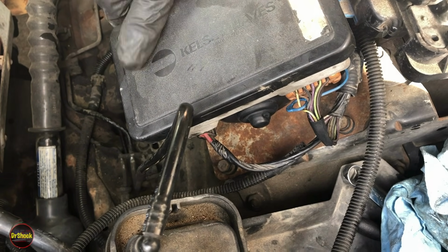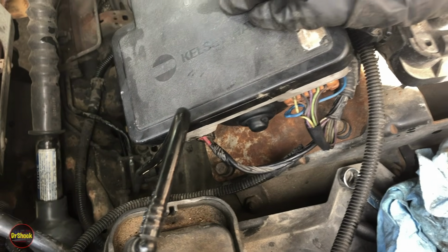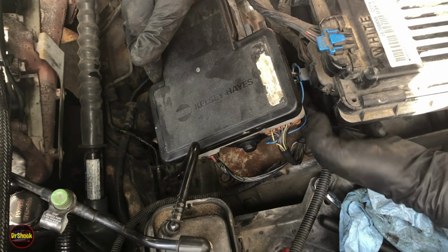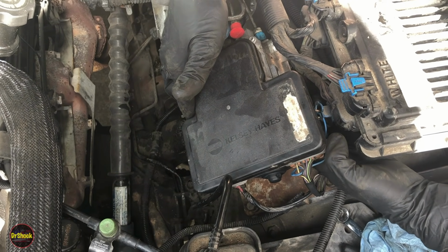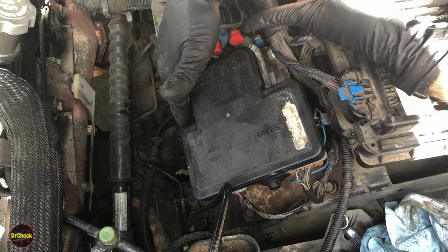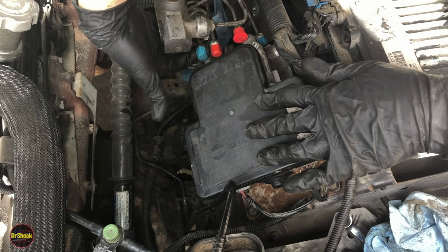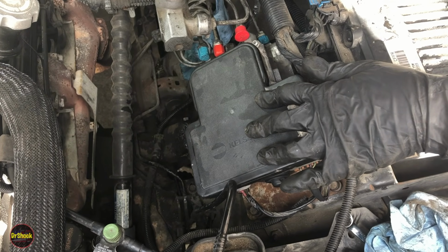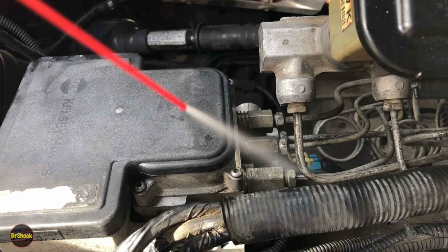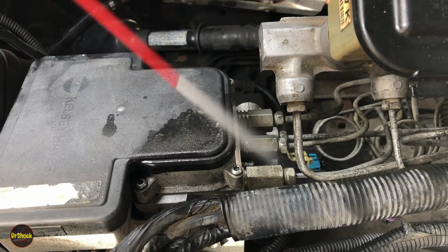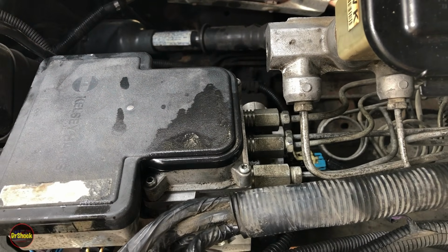We'll go ahead and put the fourth one down the lower corner there in position, and then after we do that, we'll snap the wire retainer for this harness that goes in on this side. And then we're going to, one at a time, uncap our lines and thread them back in. So let me get going with that, and we'll come back when we get ready to tighten them up. And you want to get in here with some brake clean. Make sure you got everything that you spilled cleaned up.